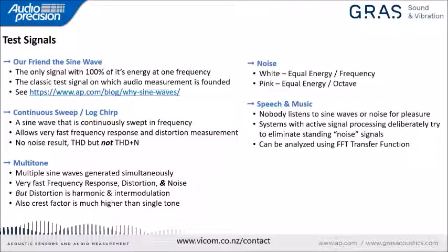There's another approach. We're still going to test with a sine wave, but what if we tested with all the sine waves at the same time? So there is the multi-tone technique, and this is literally that. We generate a bunch of sine waves simultaneously and we play them simultaneously. And we can capture the frequency response, the distortion, and the noise response of a device.